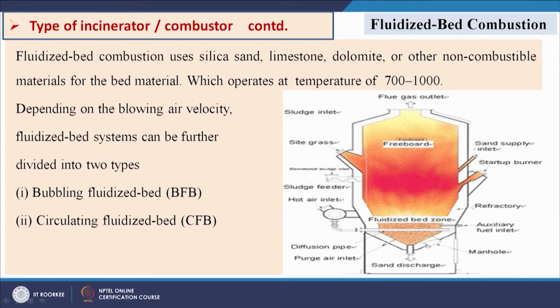In case of fluidized bed combustion, we need to use smaller size of the materials. So, this is one photograph of this fluidized bed combustor. Here the material is entering and here we are sending the air, and we have some material here. This material is used as a heat transfer media. It is heated and it is fluidized, and the solid particles and these heated materials, which we are using purposefully, come in contact, heat transfer takes place and this combustion takes place.